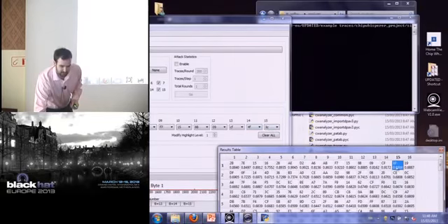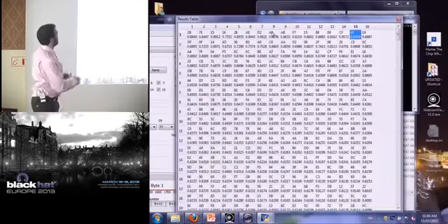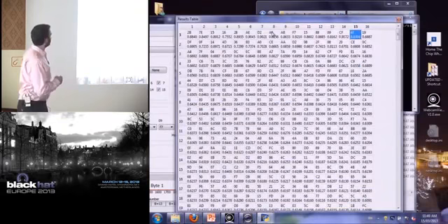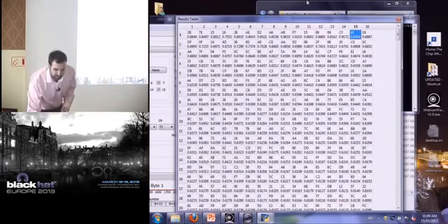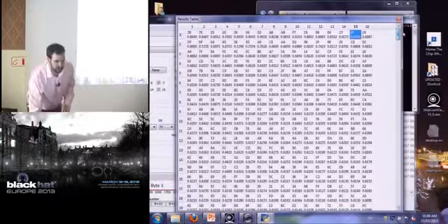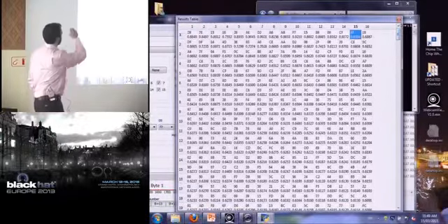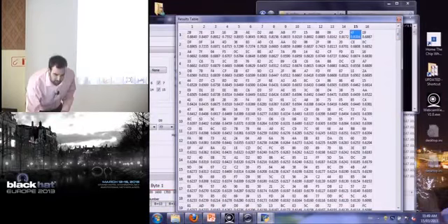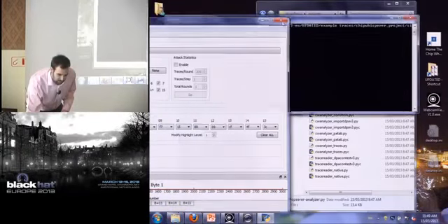So it thinks it's 4F, which is right, CF, etc. So that's just a very simple correlation power analysis. And all down this column are the 256 possibilities that the key could be, again organized by the highest correlation to the lowest. All right.